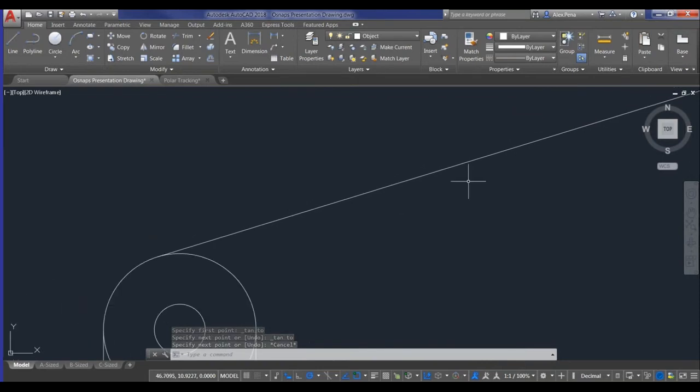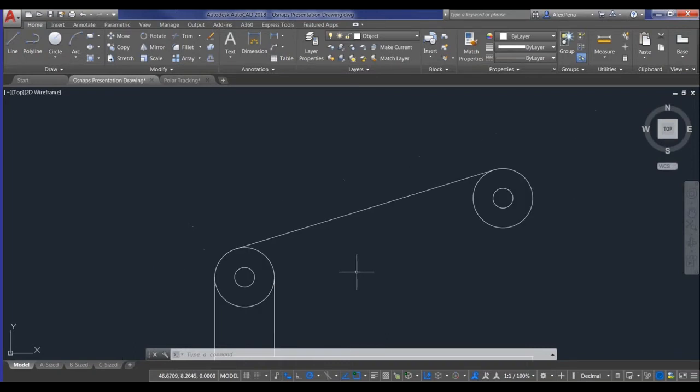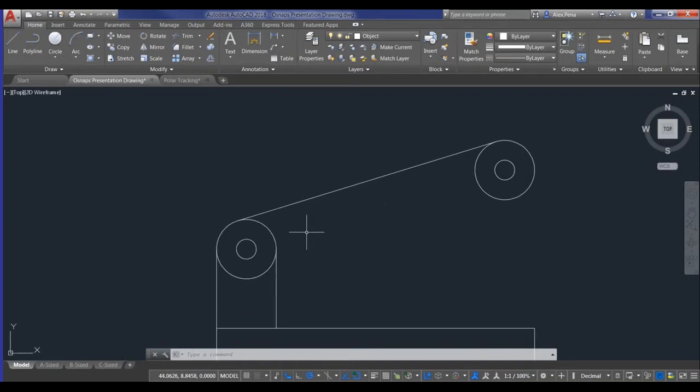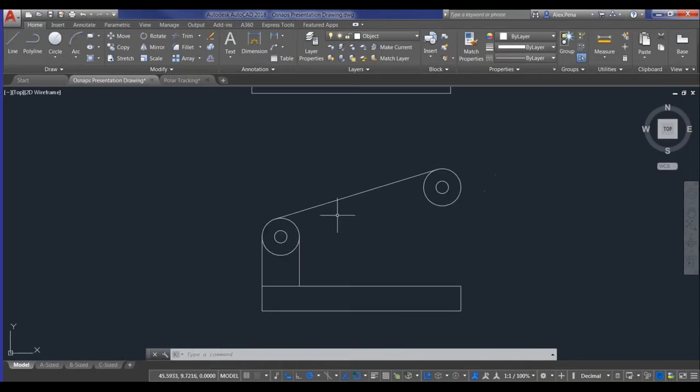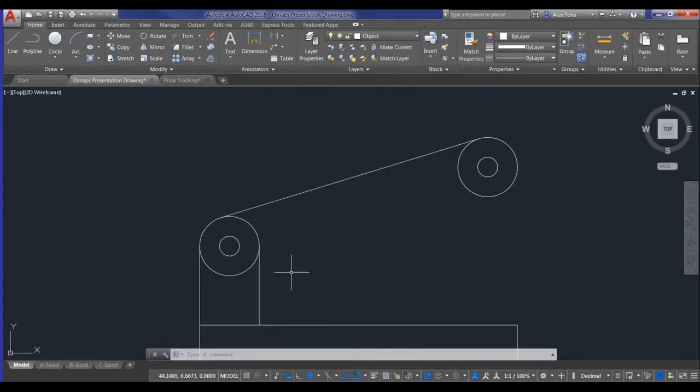You can use this, the circle command itself has an option for a tangent, tangent, radius circle and a tangent, tangent, tangent circle. And these commands are very similar to that object snap and something that we could explore later on in a webinar. Now, in order to get the same exact line as shown over here, what I want to do is go ahead and do the same steps we've been doing.